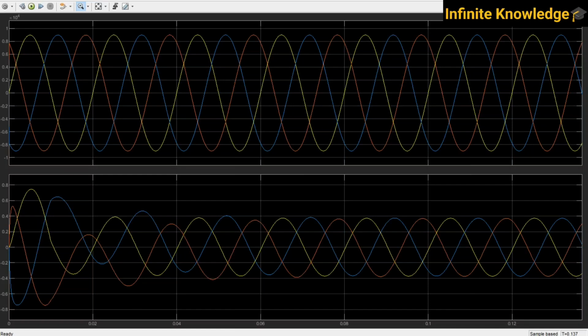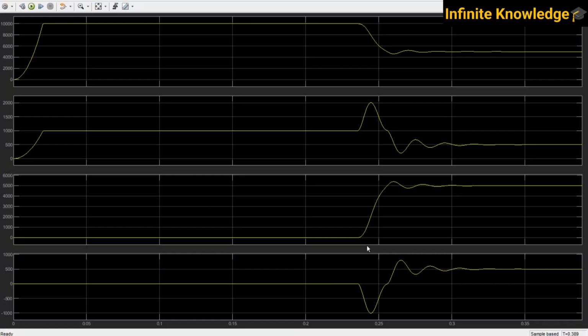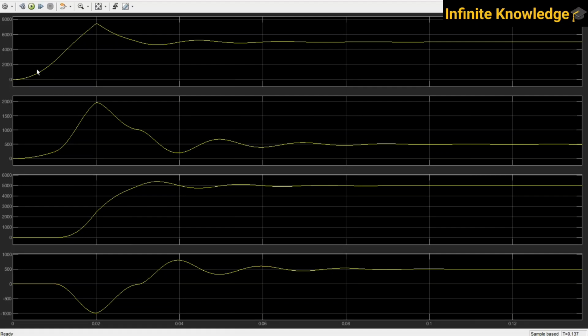Okay, so it is clear. Initially this breaker was on, that's why high current is taken, and at some time generator 2 comes to the line, and that's why current is reduced, and after some time everything is very stable. And if you want, you can check this. Initially all the active power was taken by the grid. But at this condition we have started the new generator, and right now the new generator comes into the picture, taking some active power, taking some reactive power, and that causes a reduction in the grid input.